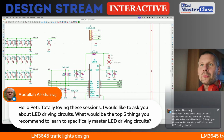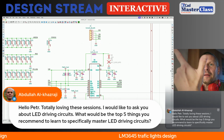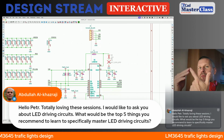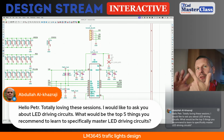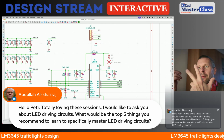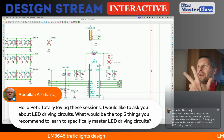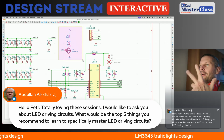So back to Abdullah's question: reverse voltage, forward voltage. Forward voltage is the connection between forward current and forward voltage. There is a voltage-ampere characteristic in the datasheet. Then drivers, I recommend simple NMOS drivers or BJT drivers with an NPN transistor, very similar to the circuit I created here.